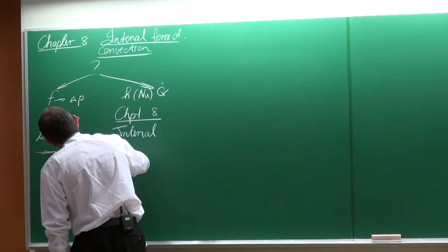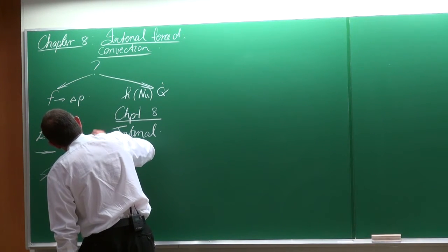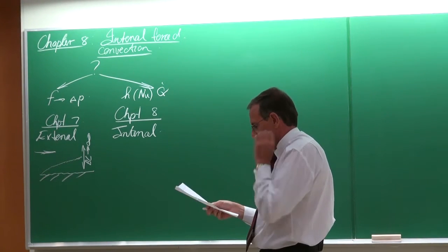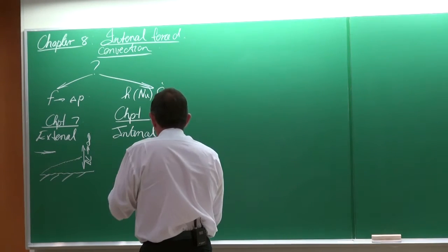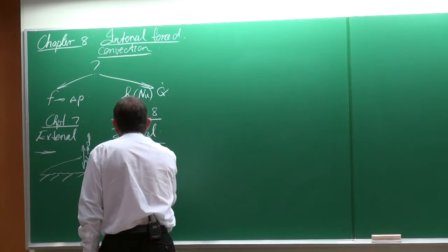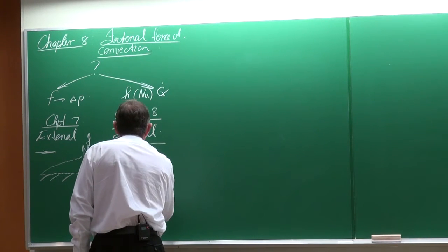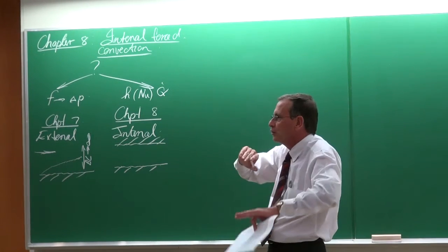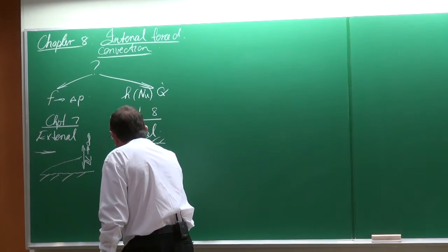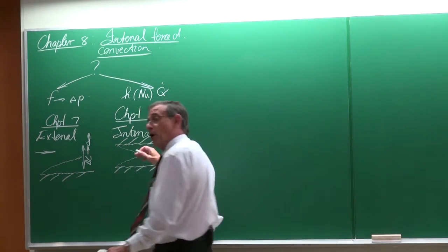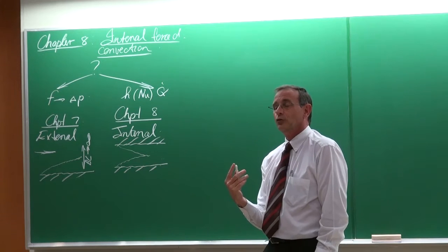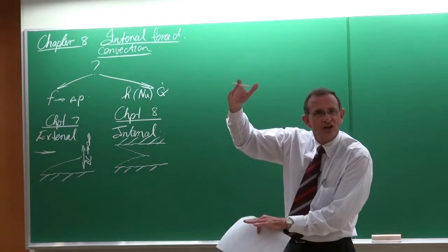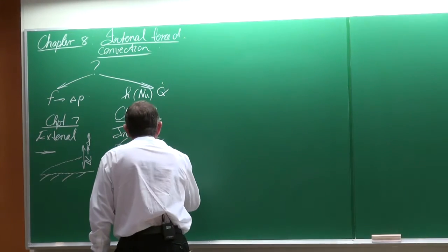So this boundary layer theoretically can become infinite. That is what happens with external flow. With internal flow, we have actually the opposite, because normally with internal flow we have two boundaries in which all the heat transfer occurs. And what now happens is that the two boundary layers grow, but they always meet, or most of the times they meet. And the boundary layer cannot become infinite in size.